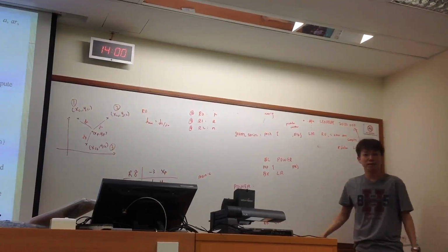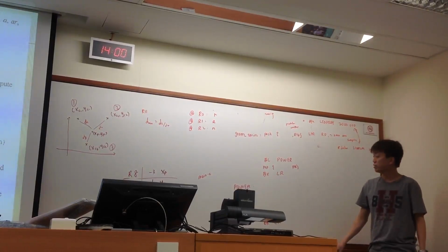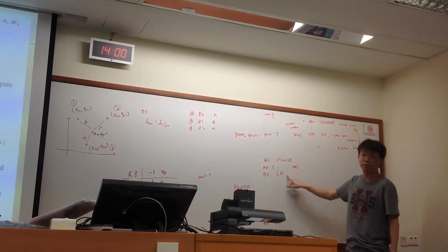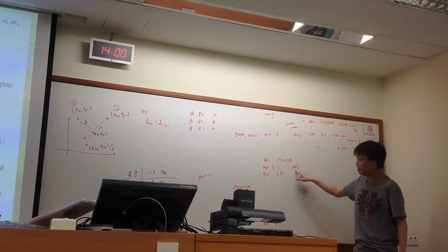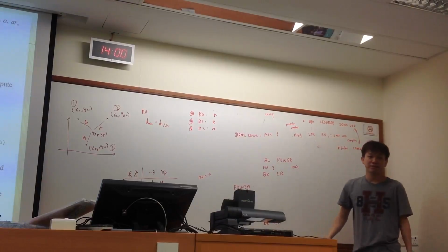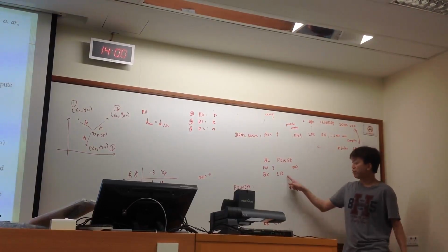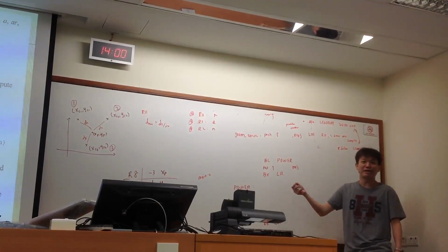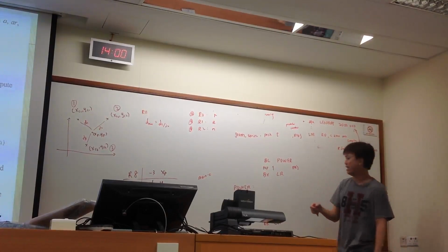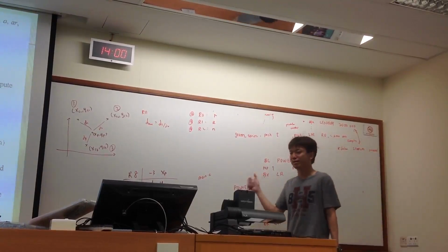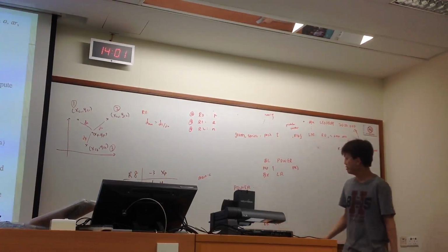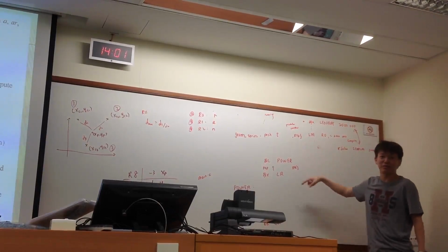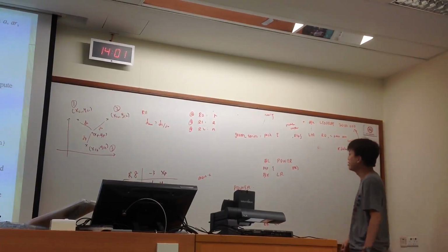Sir, if we pop to R15 straight, it will be faster. You put R15 here, you don't need to BX LR, because you put R15, you directly go back. Will it be faster compared to BX LR? You just save one line only. Faster or not? Of course faster a little bit. I think that one is not compulsory. Because normally we put it symmetric, it's easy for us to debug better.